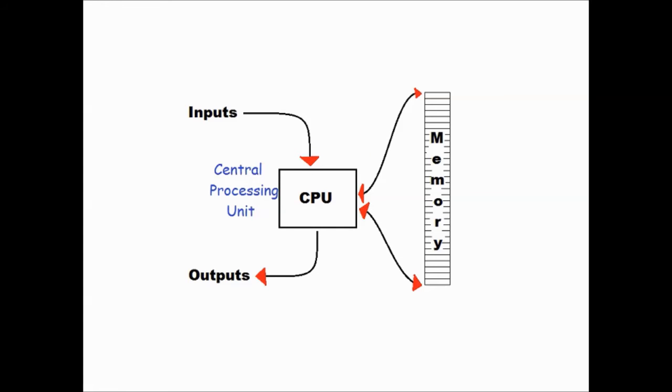Now the processor itself is a 16-bit processor, but at the time there were a ton of peripheral devices that were 8 bits, and not so many that were 16 bits, and 8-bit RAM was much cheaper than 16-bit RAM. So while the CPU is 16-bit, its data bus, the information could only go in and out of the CPU 8 bits at a time.